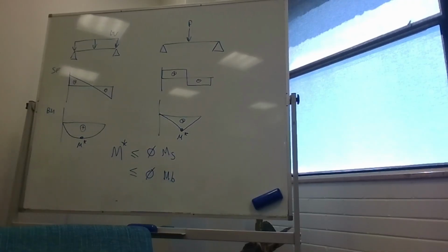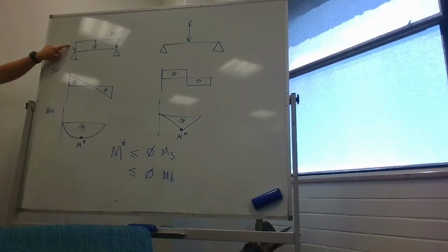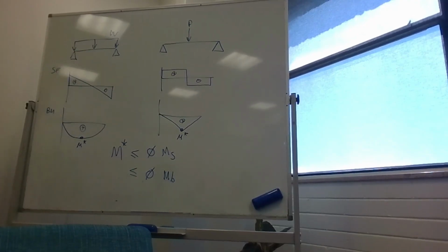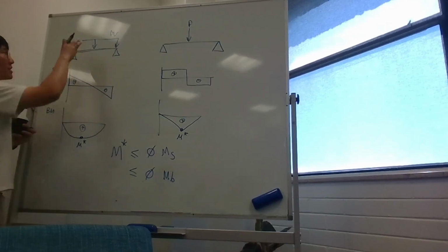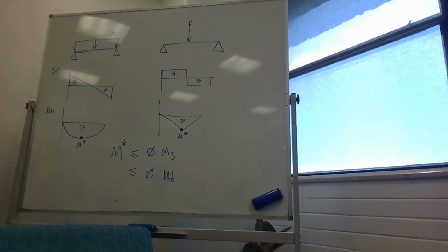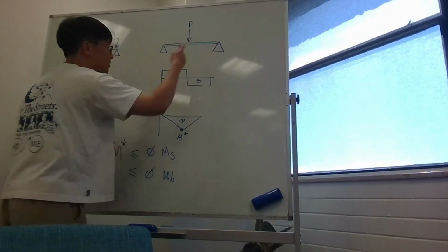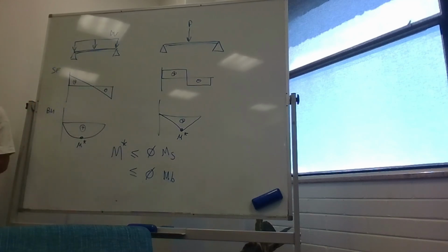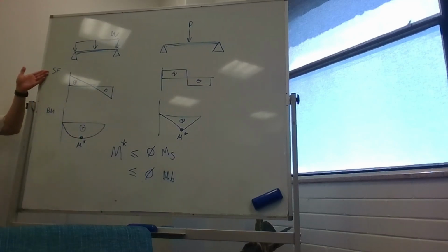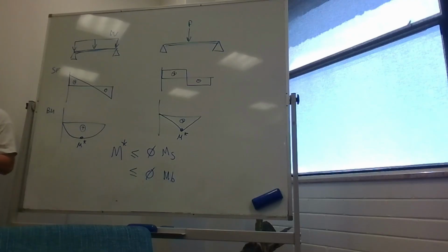So the thing is, these are the external loads, right? What's happening on this beam is that there are transverse loads. Transverse loads just means forces that are coming at it perpendicular to its long direction. And these transverse loads induce two things in the beam: they induce shear force and they induce bending moment. So two things are happening on this beam at once, but in week 4 and 5, you're only looking at one of the two.